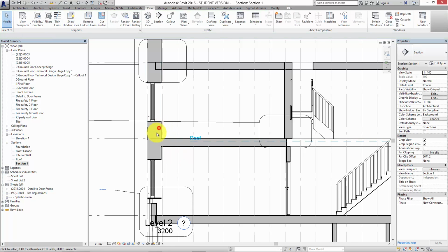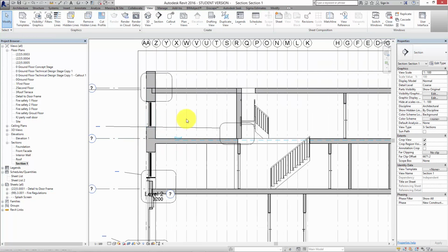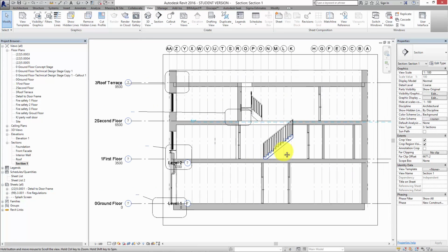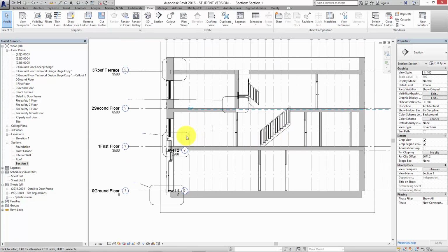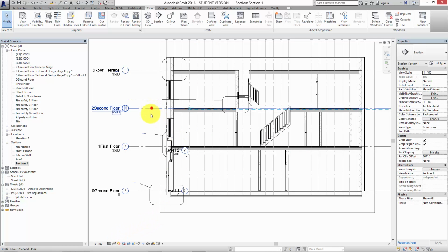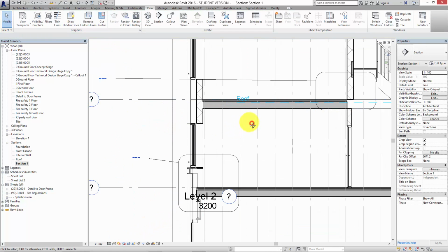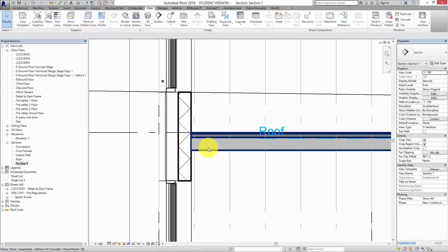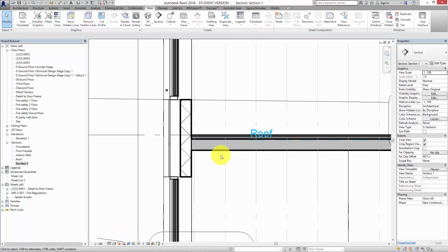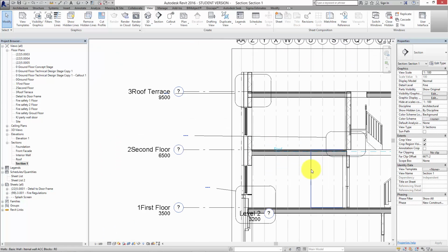And then again, if you wanted to turn that into a technical design, you turn the detail back up again to fine, and just make sure that things have the same kind of weight. So here, where we have this hatch in the wall, which is a white background with a grey hatch, just make sure everything more or less is the same kind of weight, because otherwise it just looks unprofessional if you have a floor, for example, that's just popping out of the page like that.